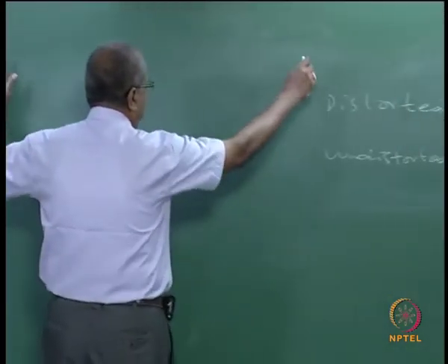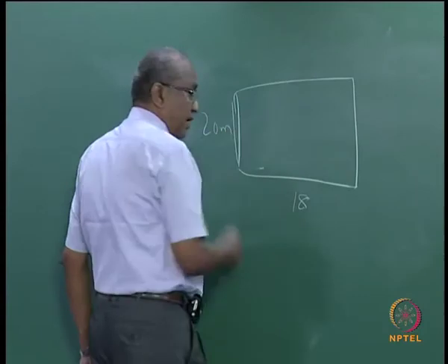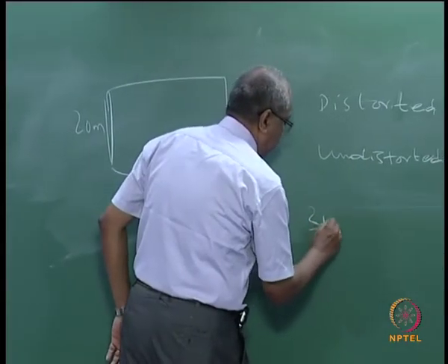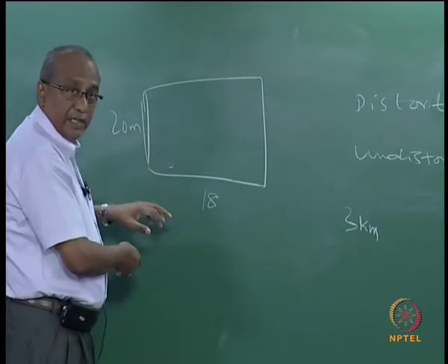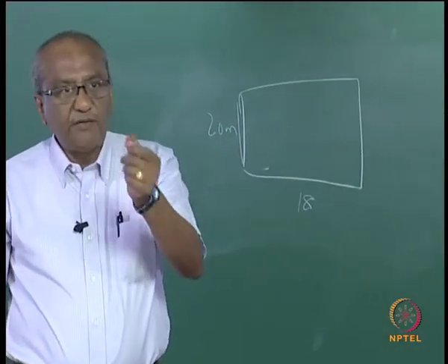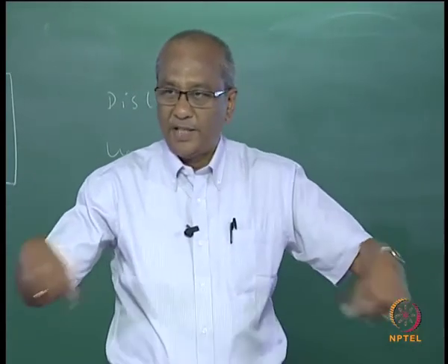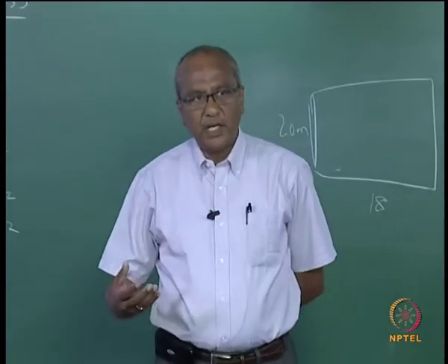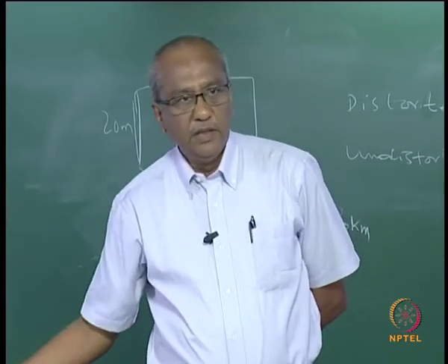That is when you want to model a basin, and your wave basin is, say for example, 20 meters or 18 meters by 20 meters in your lab, and you want to model a distance of about 2 or 3 kilometers of the shoreline. You cannot do that with the kind of scale you have, and the wave height that can be generated is maybe a maximum of 20 centimeters. So, the vertical scale has to be definitely different from the horizontal scale. The vertical scale is in terms of 20 centimeters, whereas the horizontal scale is in terms of 3 kilometers. So, you are forced to use a distorted model. Sometimes this may give some problems. Another thing is, if you want to include the sediments, then it becomes very difficult. That is a problem both in numerical as well as in physical model studies.